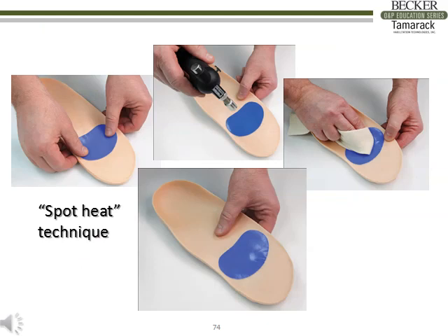For deeper pressure reliefs, some skill is needed to install the patch. The spot heat technique for medium depth contours is our favorite. After designing the coverage area and making sure the surface is clean and dry, place the patch into place, pressing lightly but not setting the perimeter of the patch. Then use a focused heat source to warm the center area of the patch.